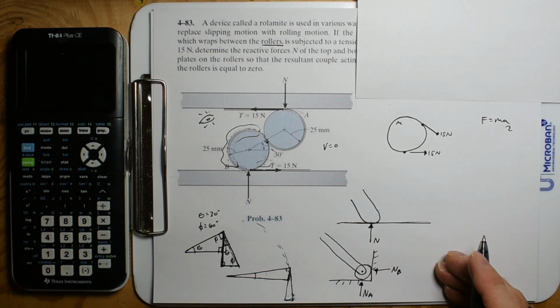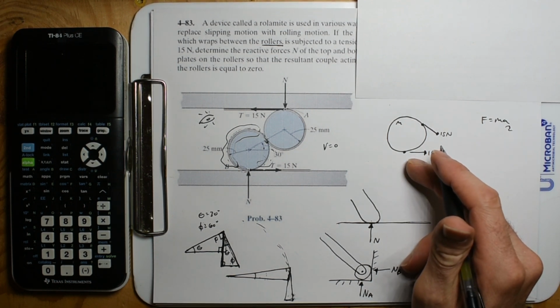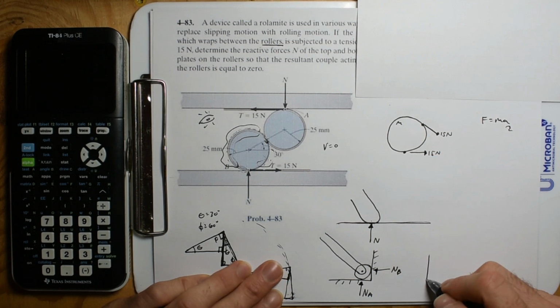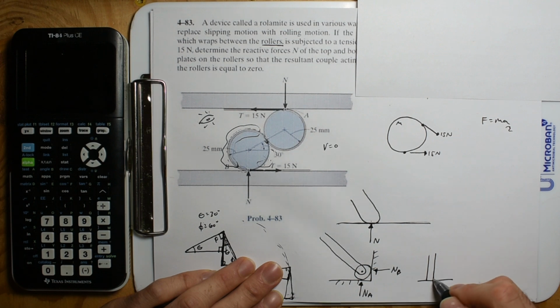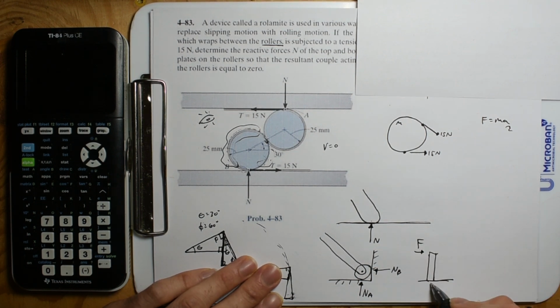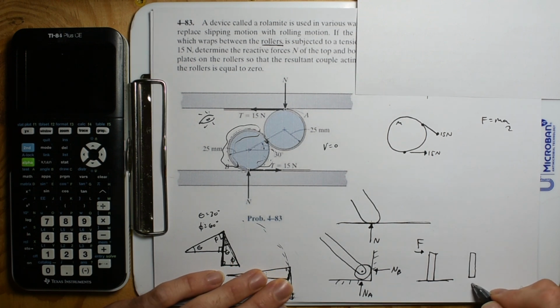All right, and then at contact points you could have a variety of things. If you have something that's welded to the ground and you're applying whatever forces up here, and you cut it from the ground, you could have a normal force, you could have a shear force, and then you could also have a moment.